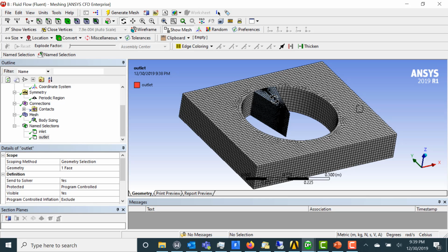You can get a good steady state solution. And what the mixing plane model does is a circumferential smearing of the velocity field between this 30-degree wedge component and the 360-degree stationary interface for the duct. So it is a powerful tool for turbomachinery, for extracting basic turbomachinery performance data without having to run a full wheel transient sliding mesh model. So let's continue with this setup.